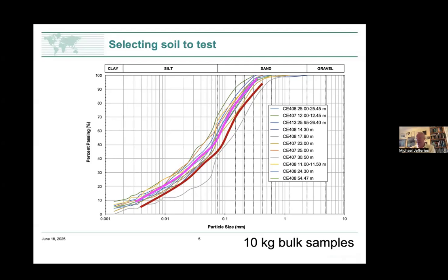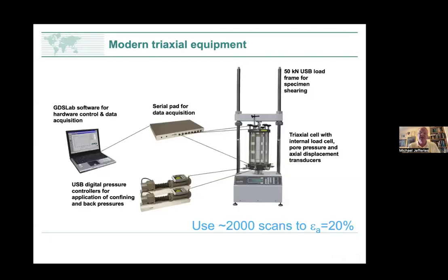And we do it by doing a program of tests for our representative gradation and then a program of tests for each of our step-out gradations. We don't do 3 tests of one gradation and combine it with 2 tests from another gradation. You have to do a suite of tests on each stockpile. Otherwise, the numbers just won't add up.